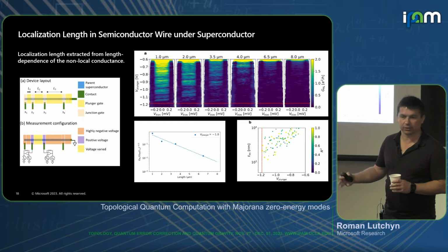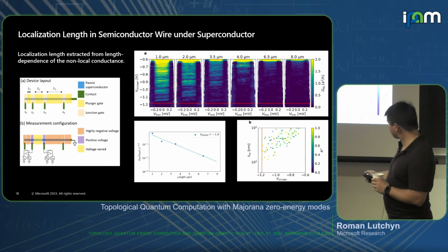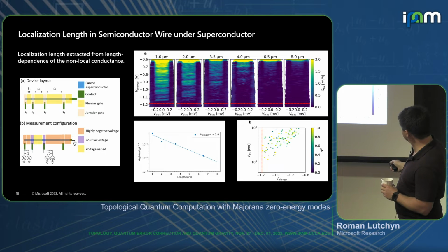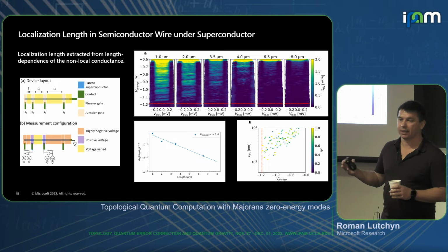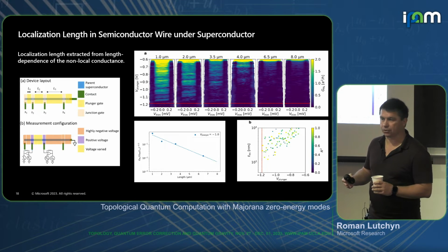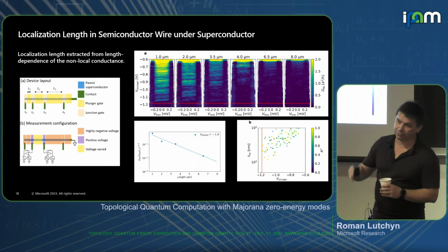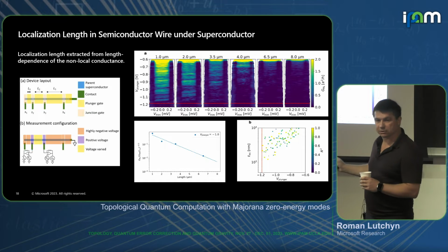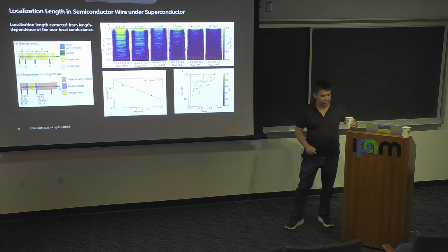That localization length tells you exactly what the disorder level is in our system. So you get the map of all these points, and the point that I'm trying to make is that our localization length in the relevant regime is larger than 1 micron, and therefore we are in a quasi-ballistic limit. Okay, so this is direct evidence, from design, then fabrication, then finally testing, that our devices are ultra clean. It's very difficult to fabricate devices that are that clean.